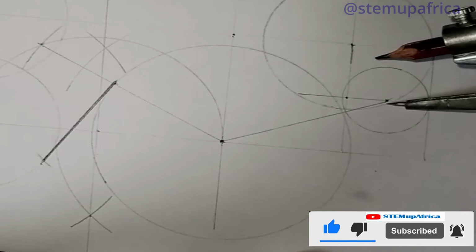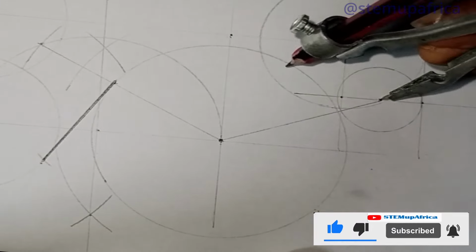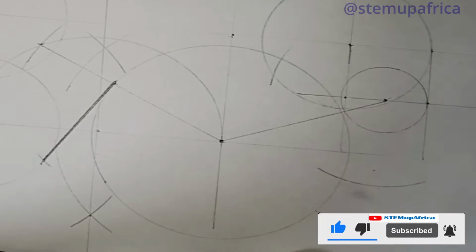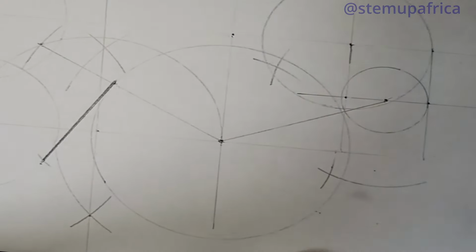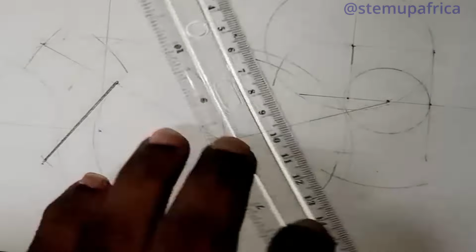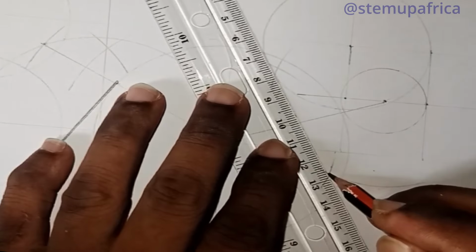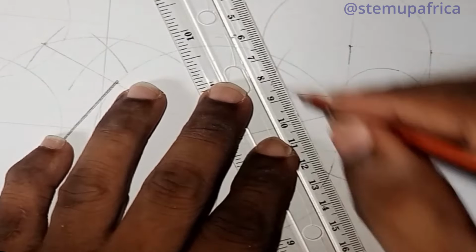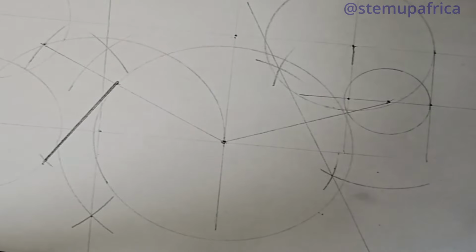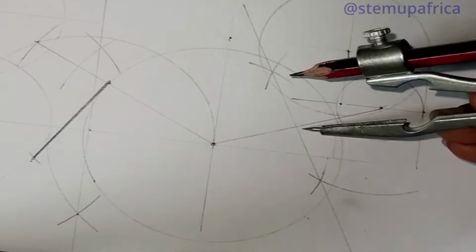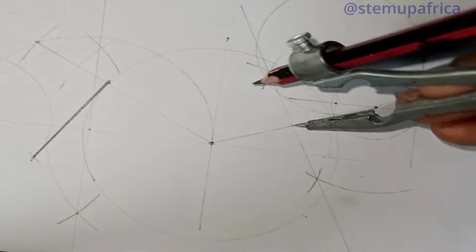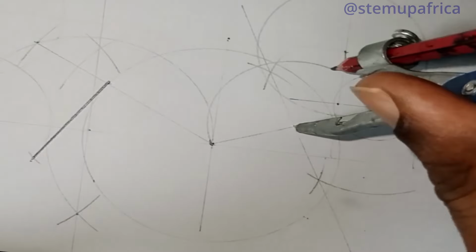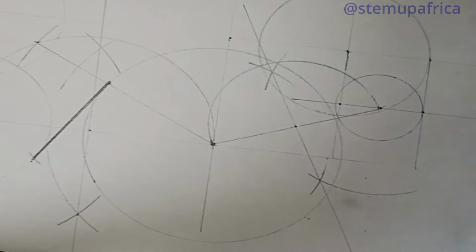I'll put my pair of compass here, draw an arc here, draw an arc here, come to this other side, intercept this arc, intercept this arc. Also join both of them with a faint line to enable us draw the semicircle. If that is done, I will put it at this point where this horizontal line touches this perpendicular bisector. I will also draw a semicircle.